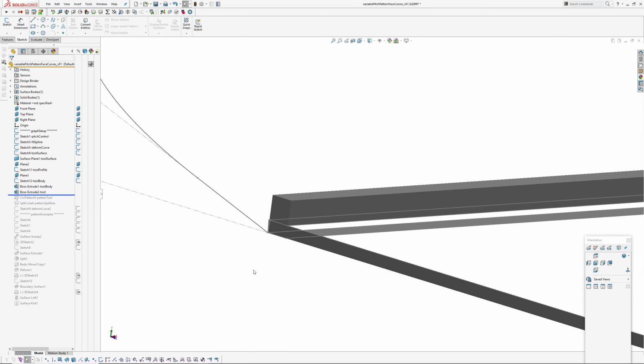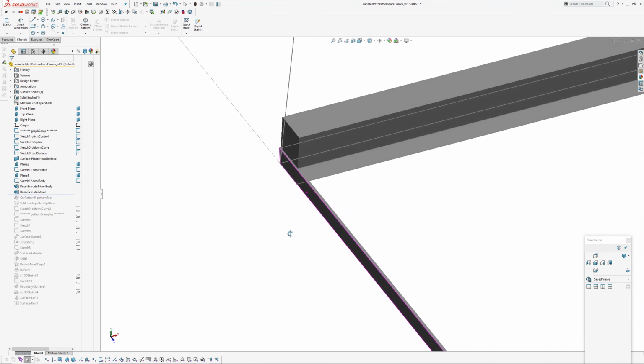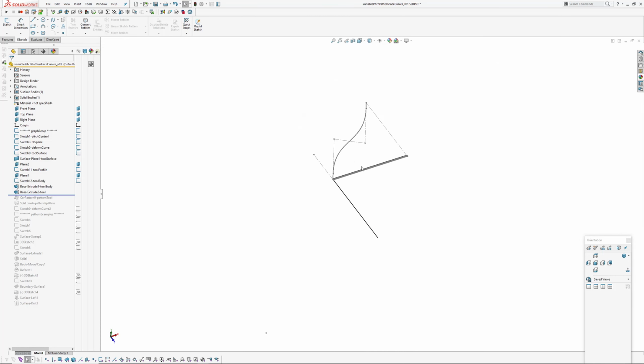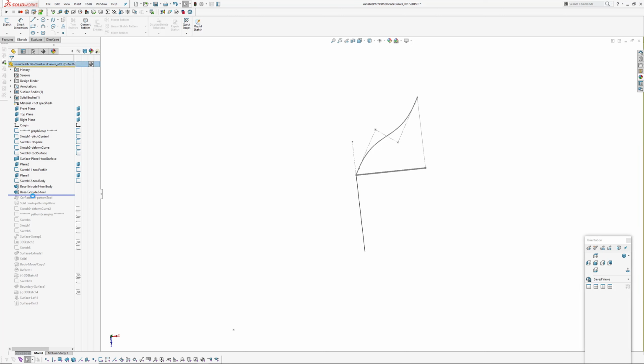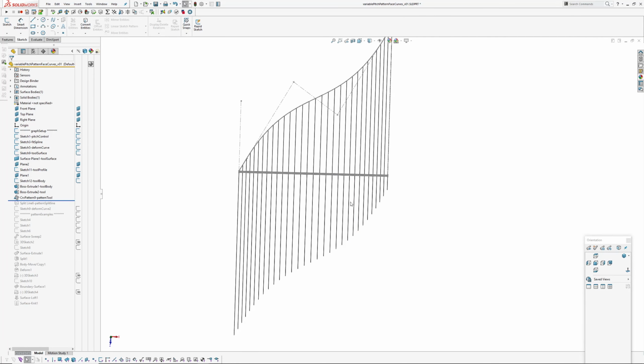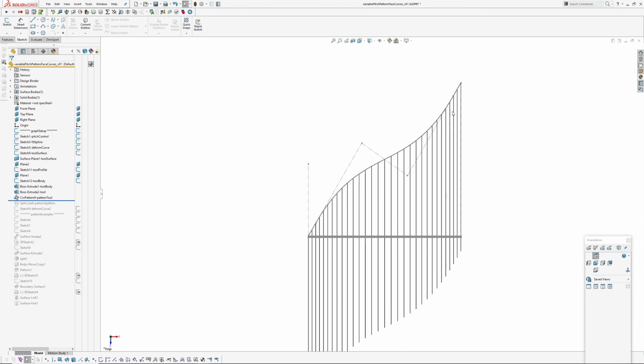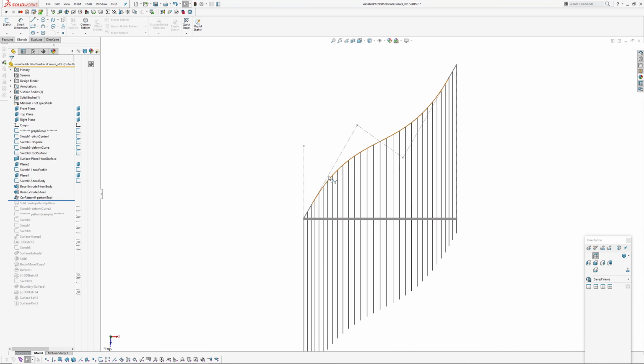And then I've made an extrude, which is the tool, and it's quite important that the tool is longer than the Y of the graph, because I'm going to pattern this wedge along this curve here, like so. And you can see, it's all very obvious now, depending on the slope of the spline, you get variable pitch across the X, because we're projecting downwards.